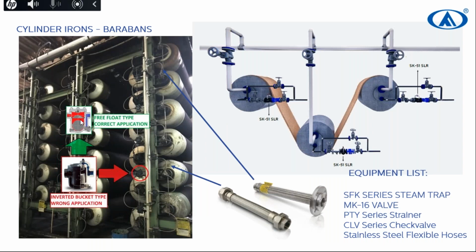And in that case, as you see here, there will be some elbows in the flexible metal hoses. You need to use an elbow type flexible metal hose, completely stainless steel, 316 or 304. Braided type flexible metal hose to connect siphons to the steam traps.